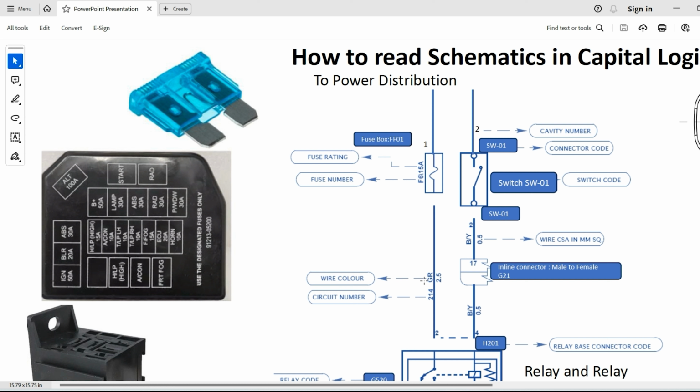This also helps in serviceability, because if you give the same color to each and every wire, then the technician or service person will not be able to identify which wire is going for which purpose. So it's always better to give different wire colors to different wires, so that it is easy for the technician to identify that this particular wire is going for this.